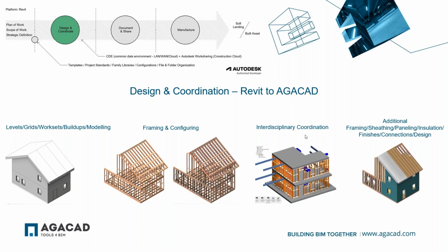And interdisciplinary coordination, so things like openings could be done with aga-cad cut opening, right? It automatically places openings in areas where you have clashes, right? So you do the clash detection and then you use cut opening to insert openings. So things like that could be really helpful.